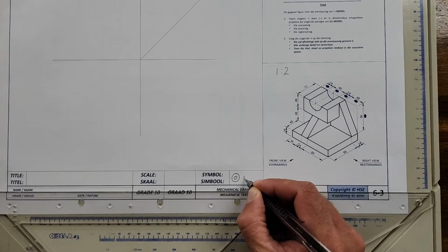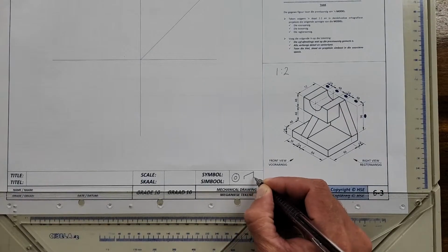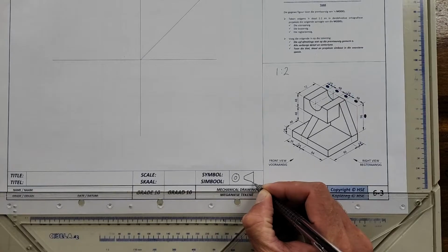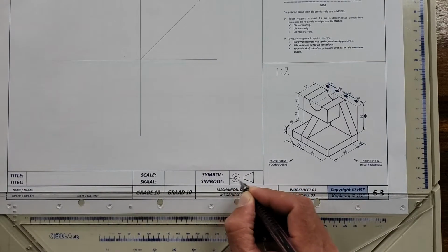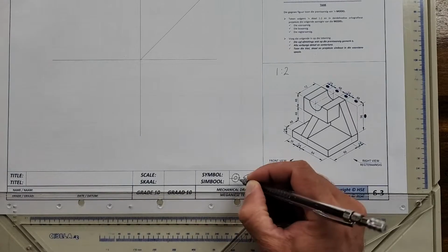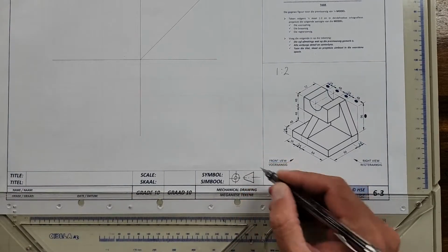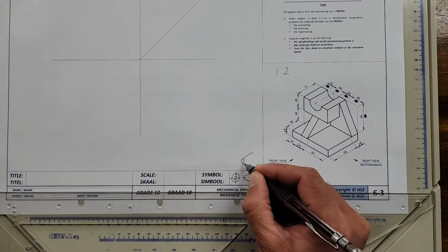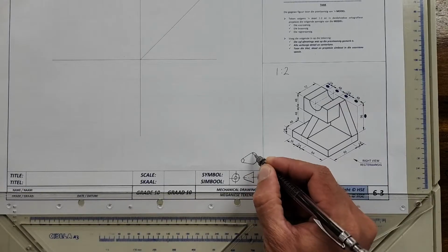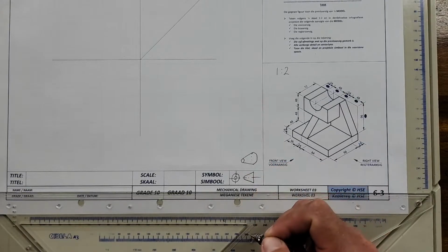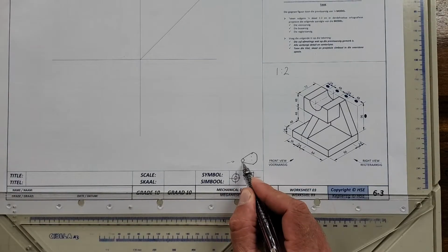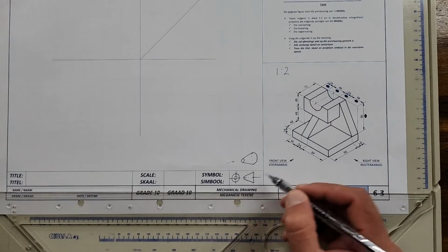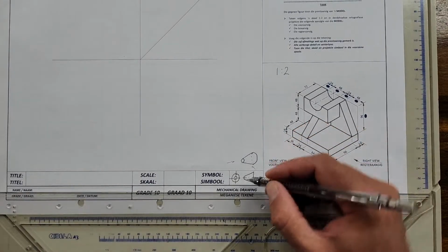And on this side, we will have the front view of the cone. Okay? This is a cone. That's the center line. Sorry about that. And we have two views here. Just a cone like this that you would see in the road. Okay? And in third angle orthographic projection, if we look from the left-hand side, we see the small circle, the big circle. And if we look from the front, well, we see this.